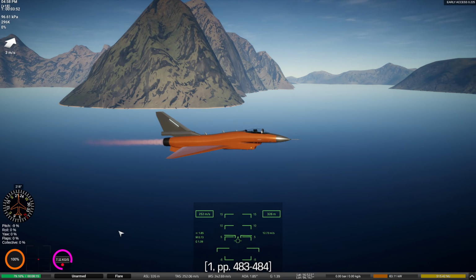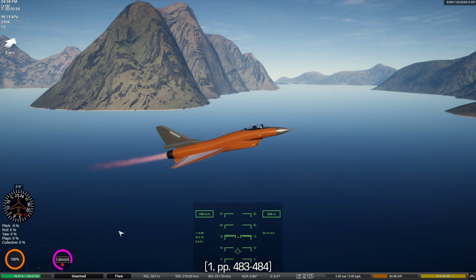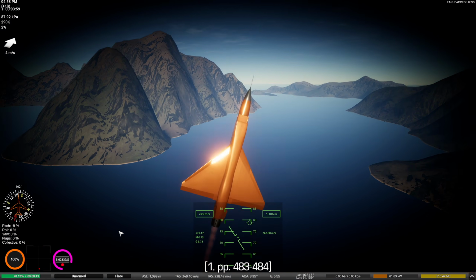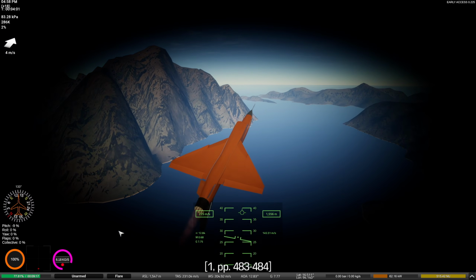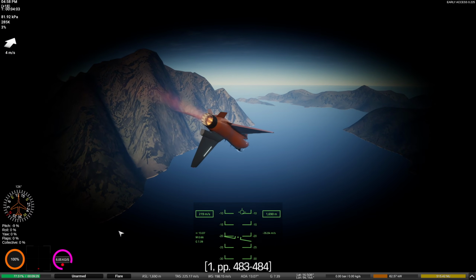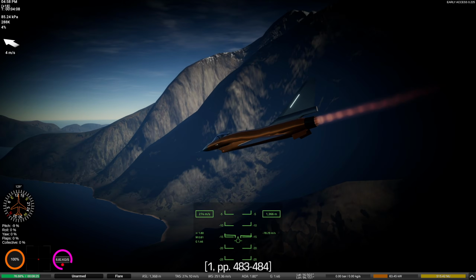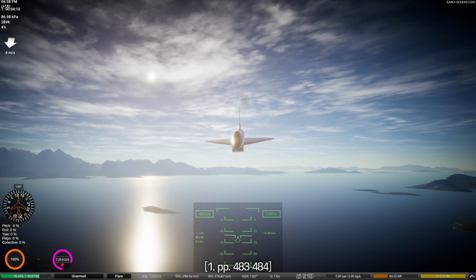One way to mitigate this is by making the leading edges less sharp to reduce or eliminate the flow separation that generates the vortices, which will significantly increase the lift-to-drag ratio, but may also reduce the vortex lifting capabilities. This can also have adverse effects on supersonic flight. This will be discussed more in a later video.